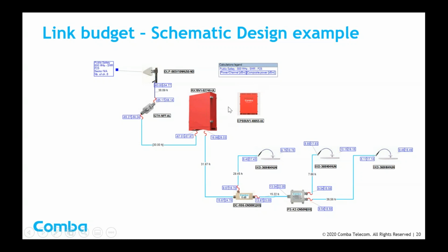I'm not going to make us go through this whole thing again. You can look at this PowerPoint later. But if you follow the signal path, each time it goes over some coax or goes through a splitter or coupler and ends up at the antenna, you'll see that these numbers go down. Why? Because every foot of coax has some signal loss. Every passive device you go through has some signal loss. There are some passive devices that can actually increase signal, so those can be used in your design. And the antennas generally provide some level of gain. Again, gain means an increase in the signal.